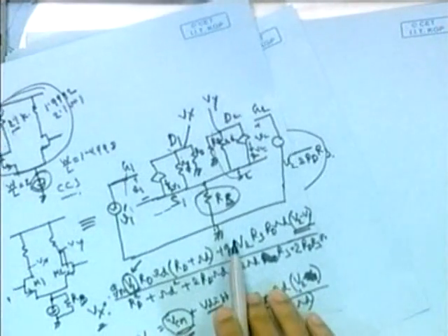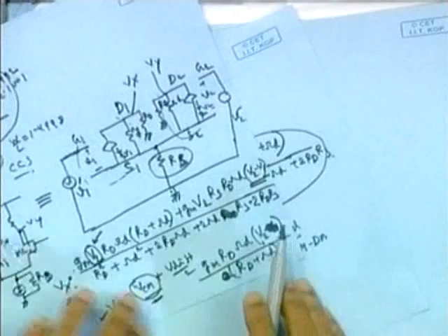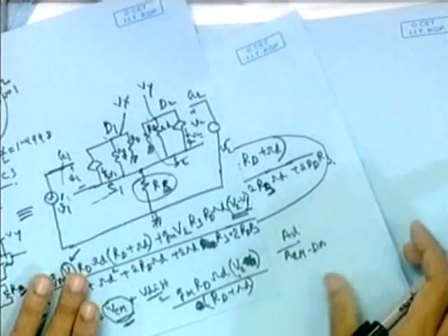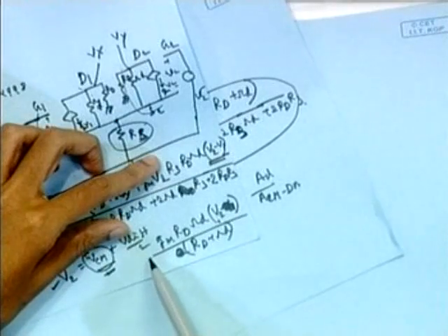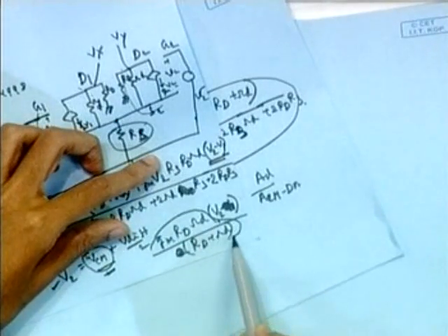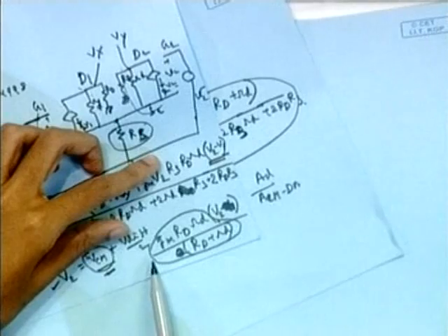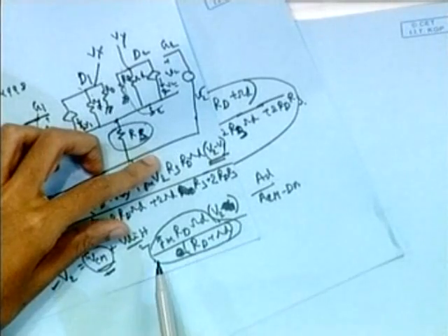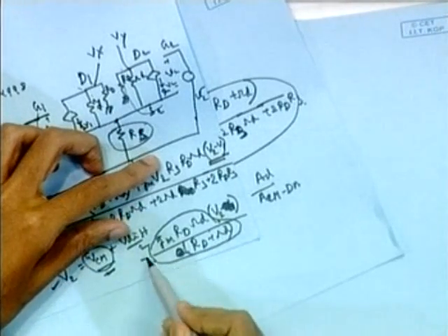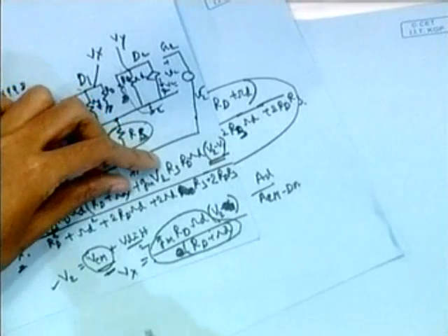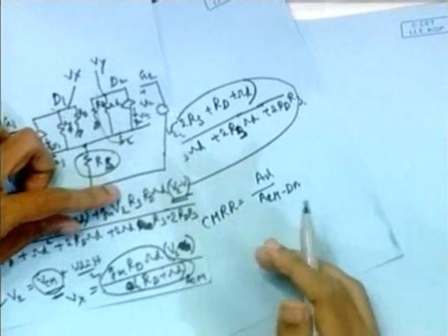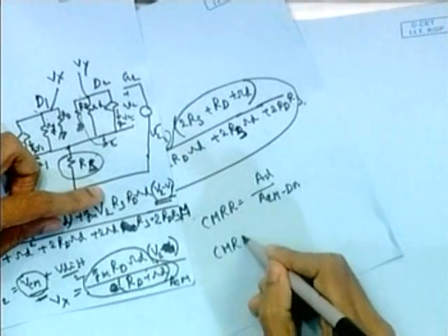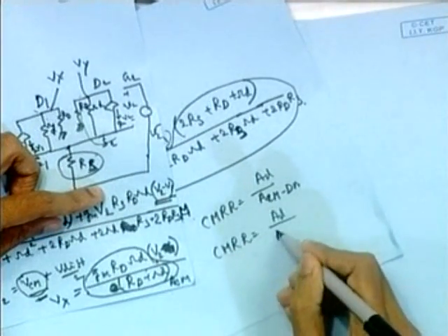for non-zero RS, we have one more CM gain, this factor, because this factor amplifies or attenuates the input CM to the output. This is our Vx, so we can call it ACM. So some people define CMRR as AD versus ACM also.